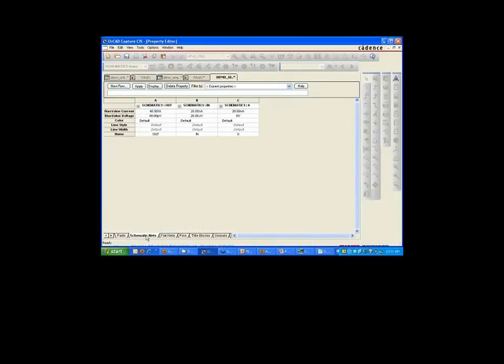With this, you can just go to your schematic nets, and you could simply sort by name right here. In my case, my design is very simple, so I don't have those nets. But you could go through and sort by those nets and then add the properties you want to across multiple pages. So that's really the end goal here, is to change something consistently across all your pages in one location. And that's the purpose of that feature.